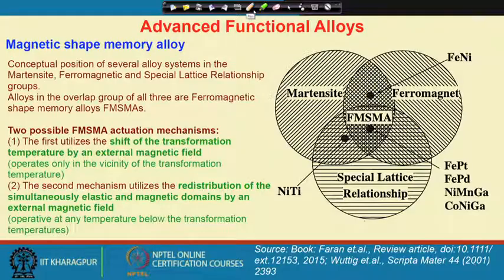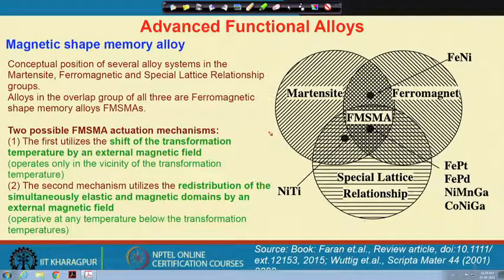Okay. So, like a structure of B19 dash, which is a martensitic structure, and let us say the B2 structure, which is the austenite structure, and those structures should transform reversibly. Definitely we also need a martensitic transformation in that case. So, let us say we have a martensitic transformation and we need some special type of relationship, so that we can get 100% shape recovery.